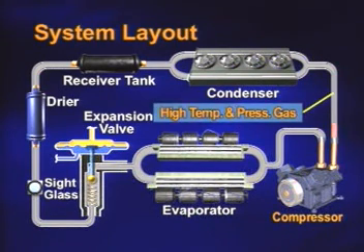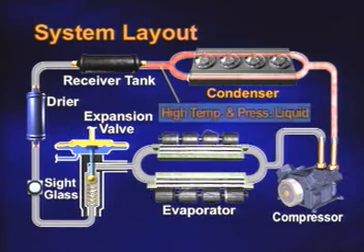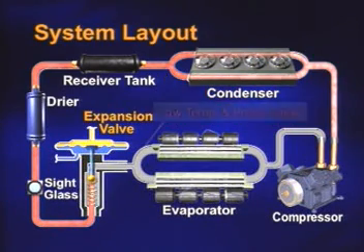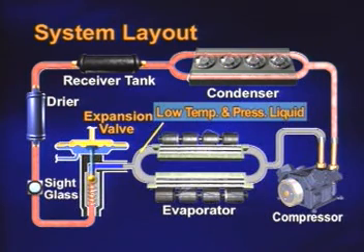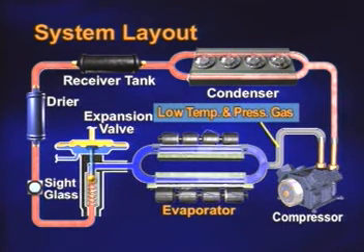Low temperature, low pressure gas refrigerant is converted into high temperature, high pressure gas refrigerant through the compressor. The condenser discharges the heat absorbed from the evaporator. Then the refrigerant transforms to liquid from gas. The expansion valve drops the pressure and the temperature of the refrigerant by expanding it to help the refrigerant evaporation. In the evaporator, the refrigerant evaporates into gas from liquid by absorbing the heat energy inside the bus. Then the inside temperature cools down by the evaporation potential heat.